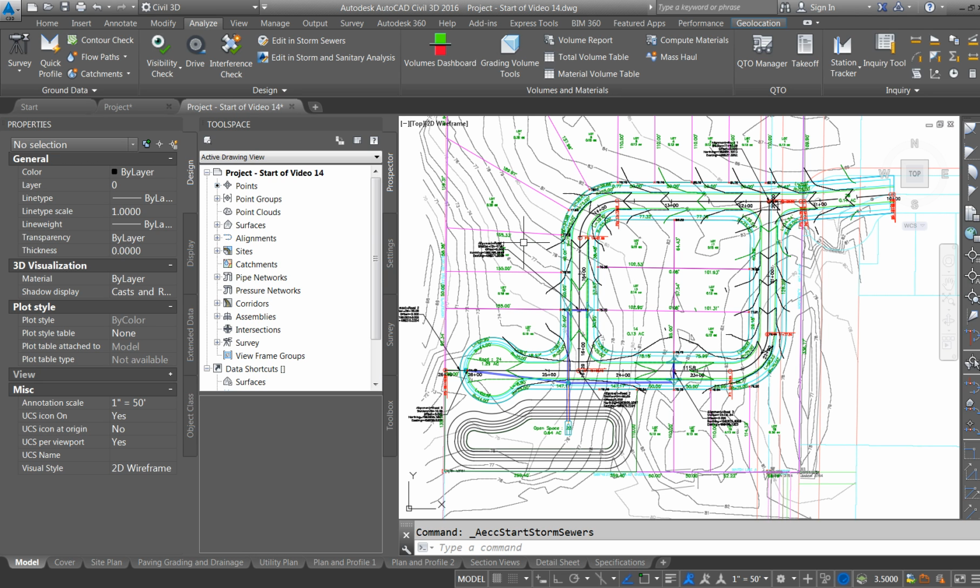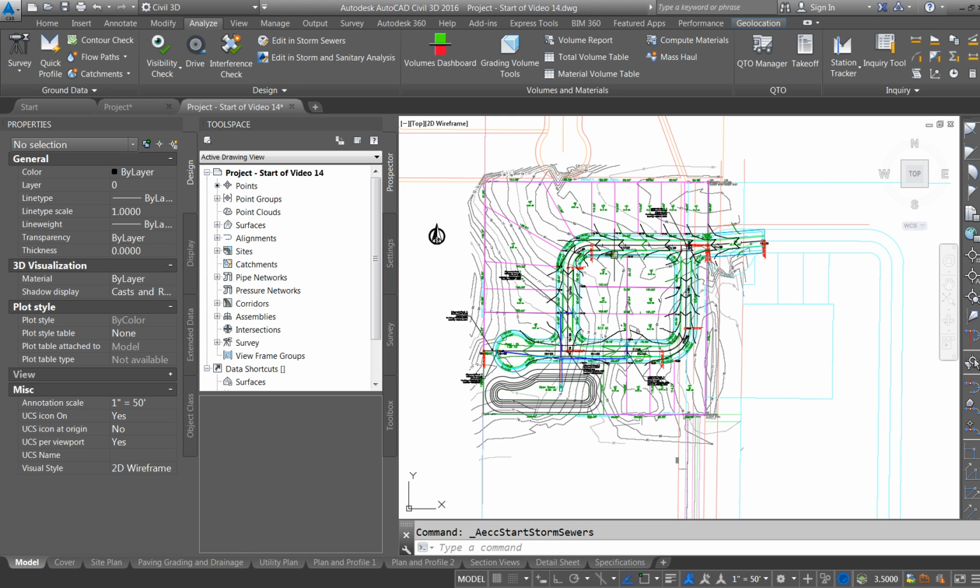Now, in a separate video, I'll show you and talk about drainage area to the structures. For example, how much water is going into this structure here. What we can do is create a polyline. Let's say we know that from this end of the street to this edge, at least half of these lots is going to drain to this storm structure, from here to possibly here.